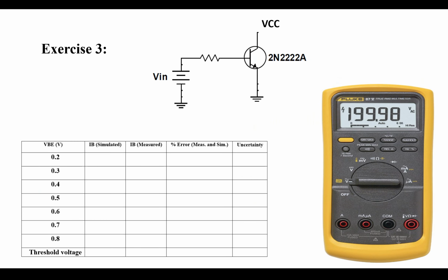No? The next one is for BJT. Now look at the circuit where you see a resistor between the input or the control signal and the base. That's why I said the BJT works with the current signal. That resistor translates the voltage into the current. Okay, so by that resistor, now you have a defined current injecting to the base. This is a KVL here.